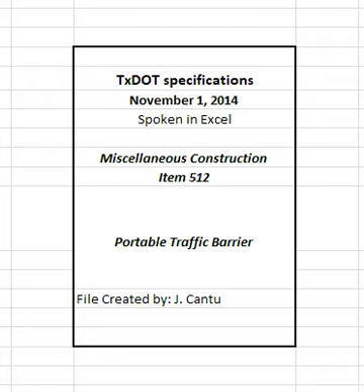2.1.2 Steel. Barrier sections will be furnished when shown on the plans. Barrier sections must meet the crash testing requirements of NCHRP 350 or MASH TL3 or TL4 specifications as per test matrix for longitudinal barriers.